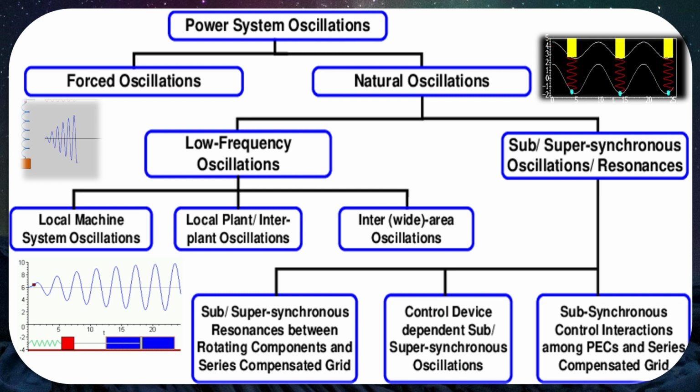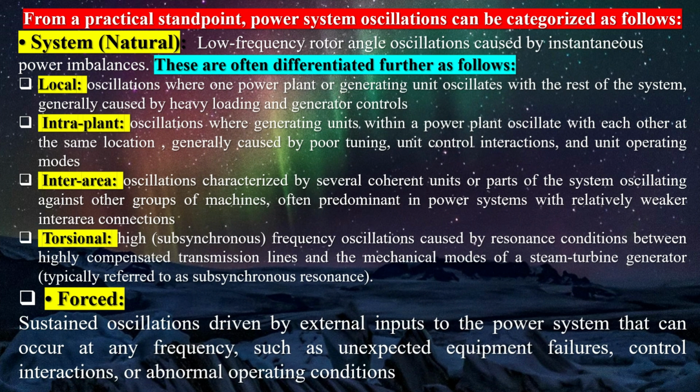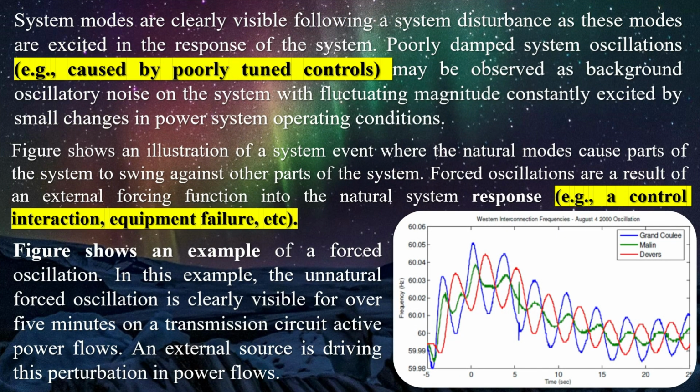The sources of these periodic inputs are varied and can include traditional generation, e.g., fossil, hydro, and nuclear plants, alternative generation, e.g., wind and solar, cyclical loads, e.g., aluminum smelting, and malfunctioning controls. The characteristics of forced oscillations include narrow frequency components, harmonic frequencies that are integer multiples, and a consistent oscillation frequency throughout the system. The shape of the oscillation is observed in the amplitude and phase in different parts of the system.